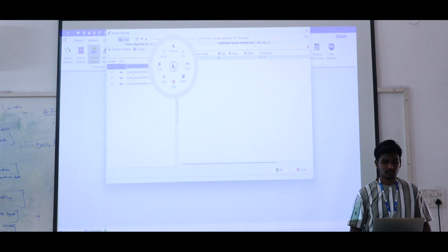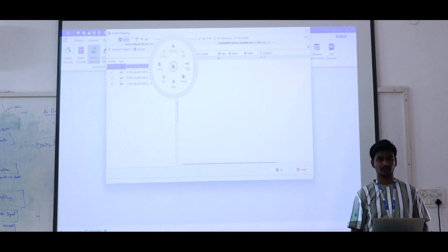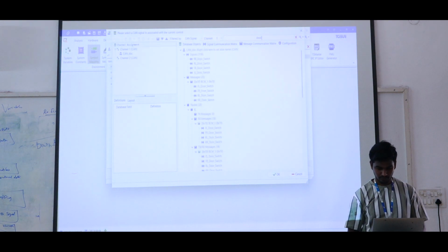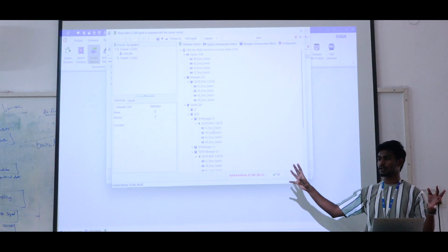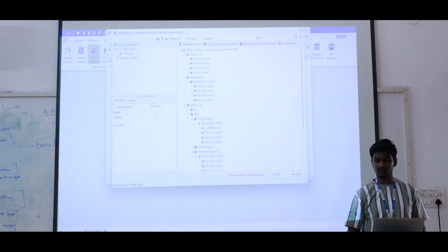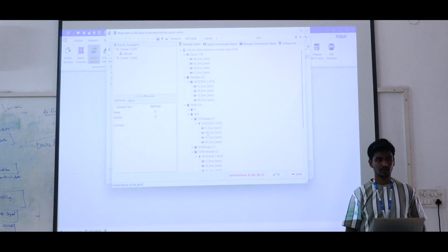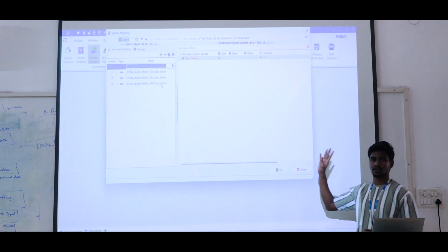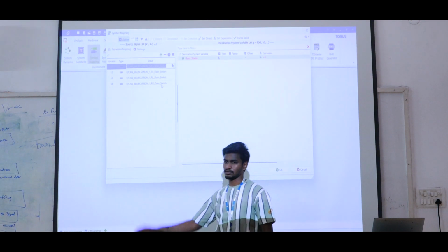Transmitter. Go to the scanner, you just search for door. Here you have to search for door. So in this node we are having a body control module because this door switch is available in our body control module only. So I am mentioning the body control module as the transmitter. So you have to select 4 door switches for 4 different values. First one FR door and then click OK. And then second FR door, third RL door, fourth RR door. 4 different kinds of doors you have to select here.